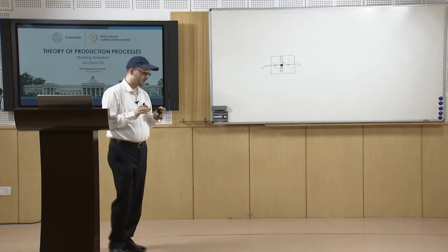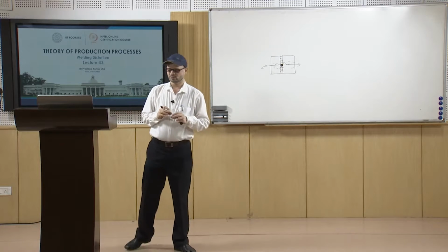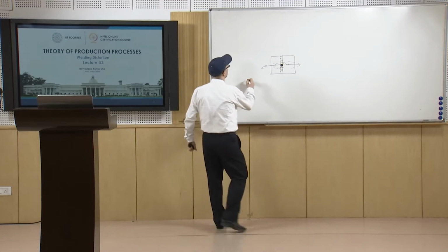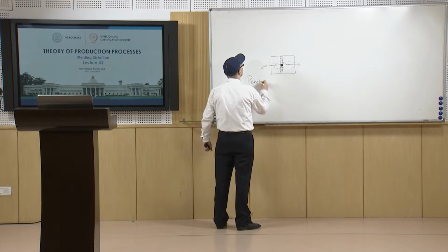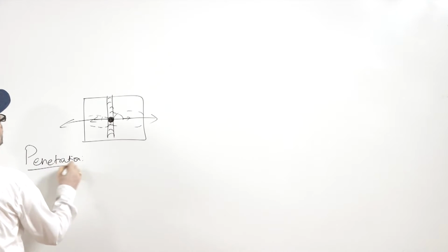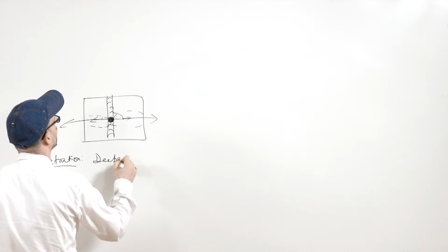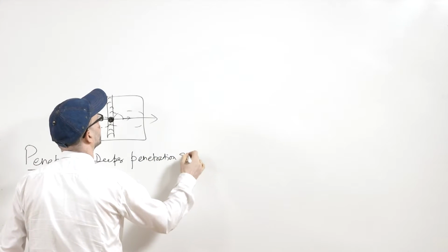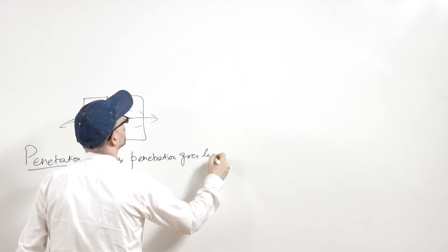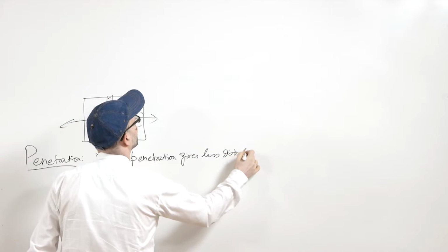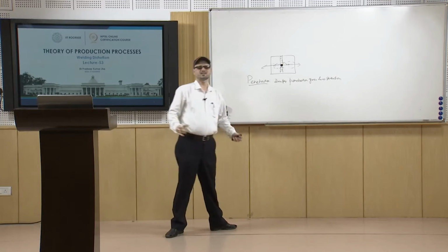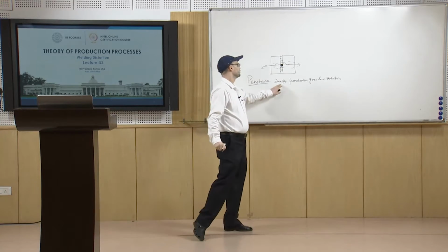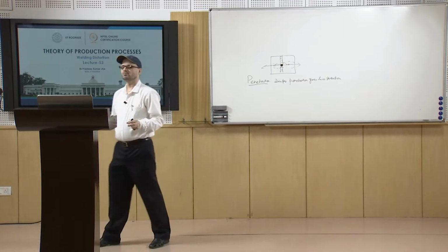Then the penetration. If you talk about the penetration, deeper penetration will give you less distortion, maybe because it will hold the plates with more strength, so the chances of distortion will be lesser.